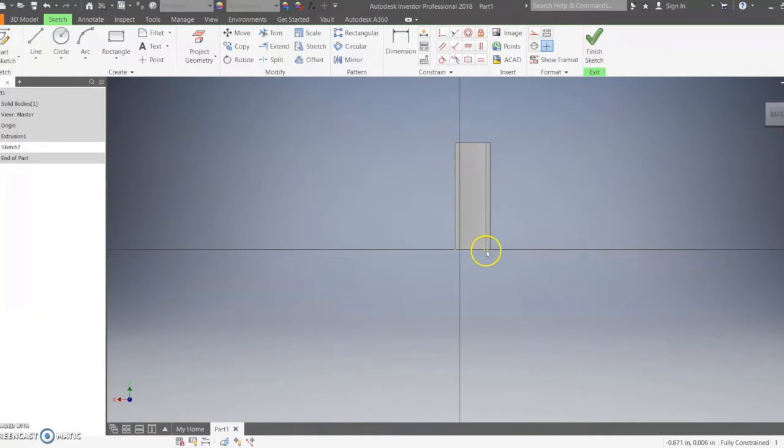Make sure you know the X and Y dimensions of your holes before you actually plot them. Because what you can do is you can plot X this way, Y this way. So it'll be easy to plot the holes. For example, we're going to have the two holes be 0.75 and 2.25 respectively, and both of them are going to be 0.5 inwards from here. Note that our reference point is this edge rather than 0, 0, so make sure that when you're creating your actual part that you take into account your reference point.